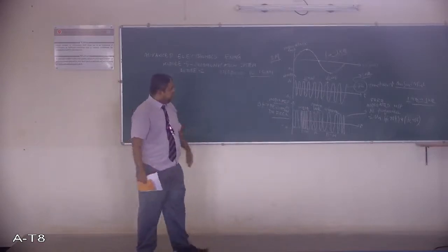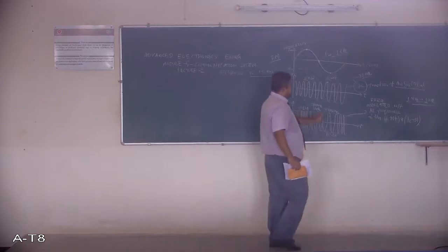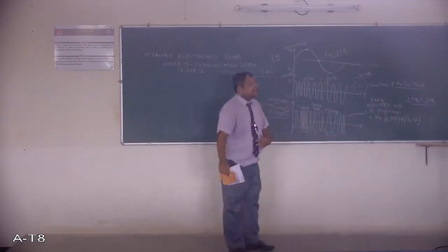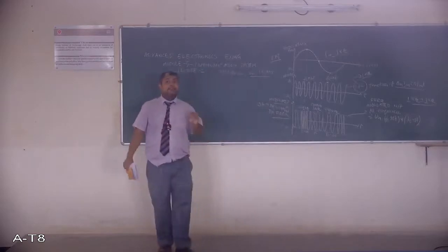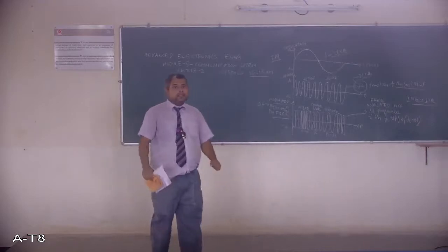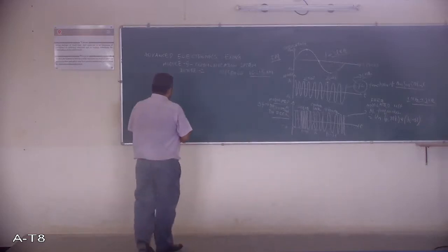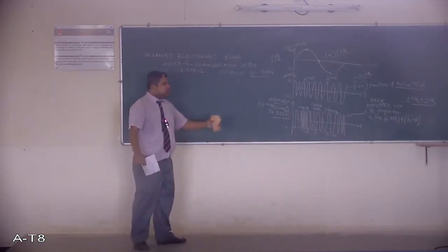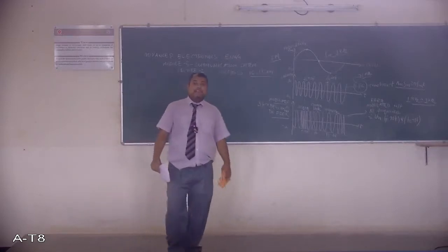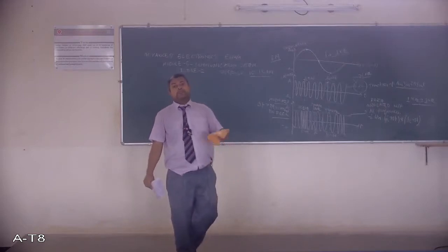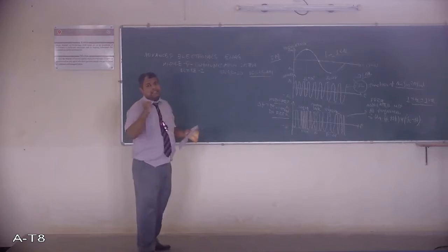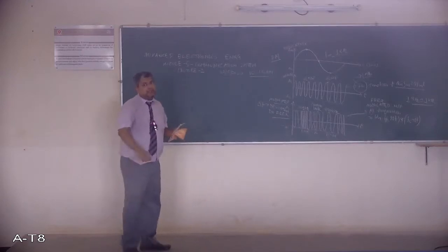And we have to remember that the frequency of the FM waveform is ranging from Fc plus minus delta f, where delta f is called the deviation. That frequency deviation is caused by the amplitude of the modulating signal. So this is a very important definition for frequency modulation. It is a modulation where the frequency of the carrier signal is changed as per the amplitude of the modulating signal. So that is FM. Now let us see some of the features of the frequency modulated waveform.